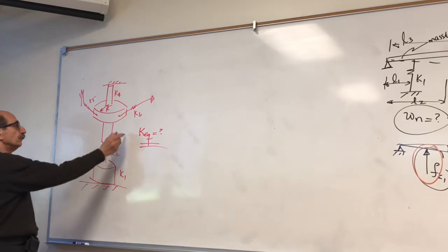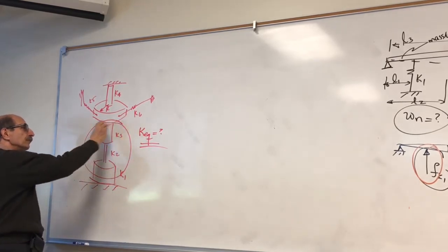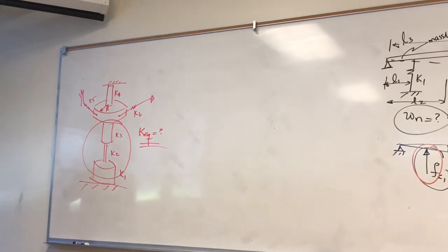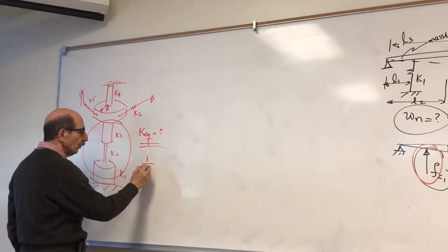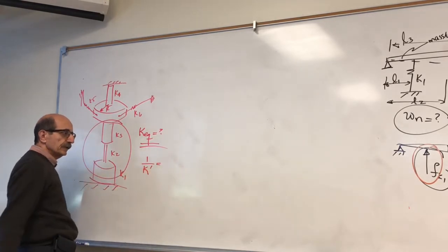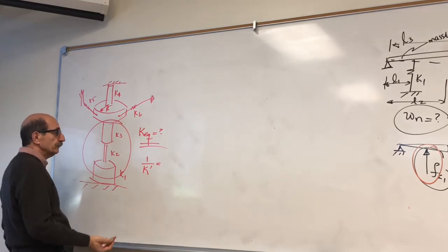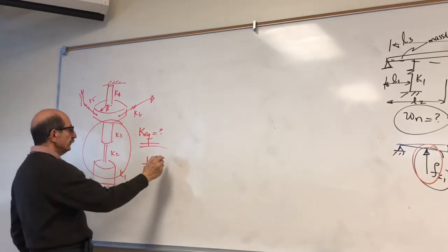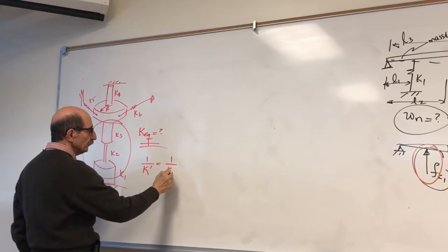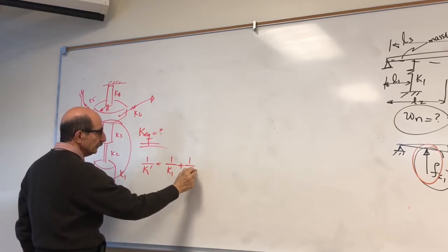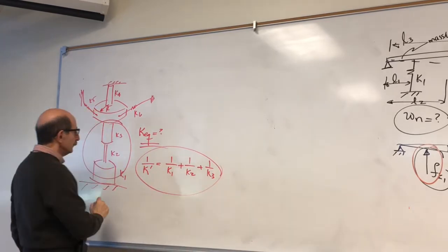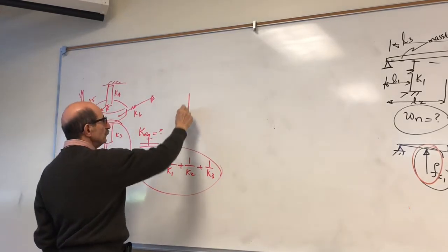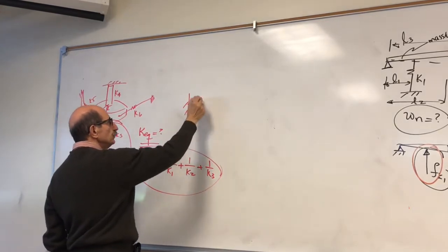So, therefore, if these 3 are subjected to the same force, you can replace that with a single stiffness. They're in series, so you can find that single stiffness from this relationship, right? So then the problem is reduced down to this.